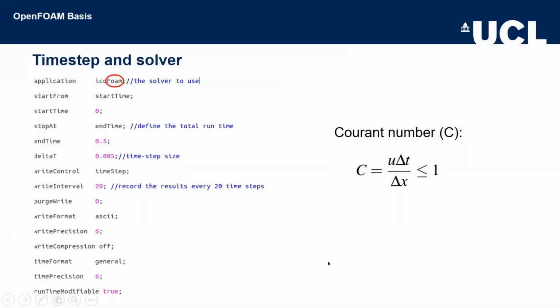Usually the name of an OpenFOAM solver ends with the word FOAM with the uppercase F, and the prefix depends on the solver type. For example, interFOAM is a solver for two incompressible fluid simulations, and FSIFOAM is to solve fluid structure interaction problems.